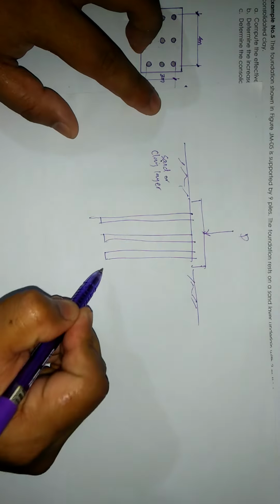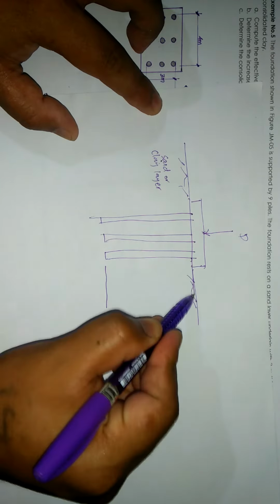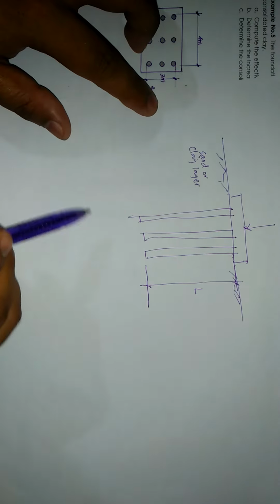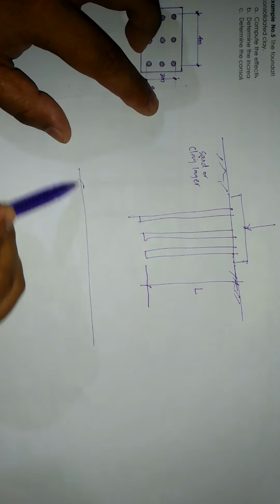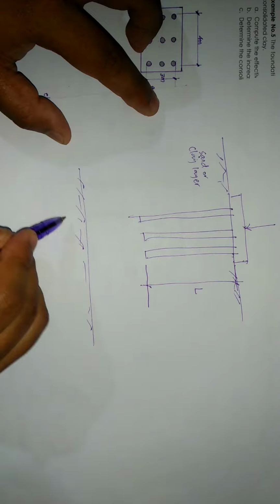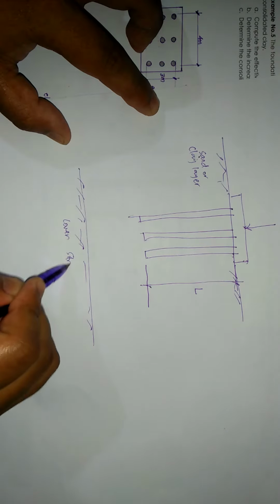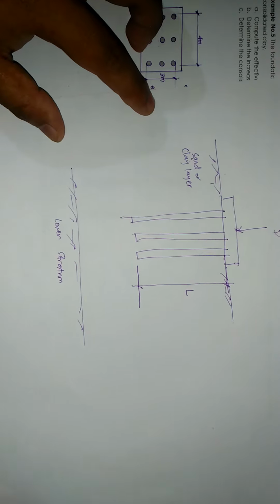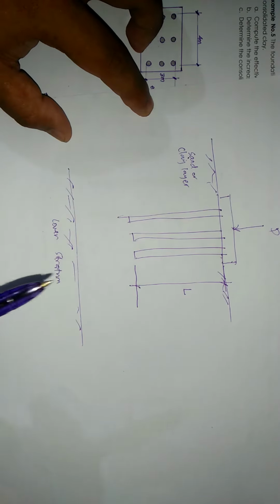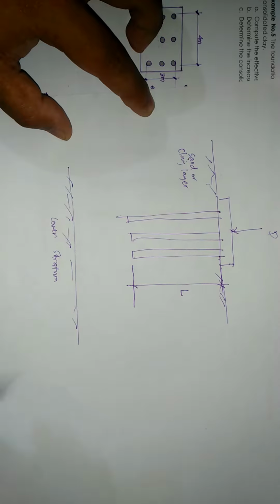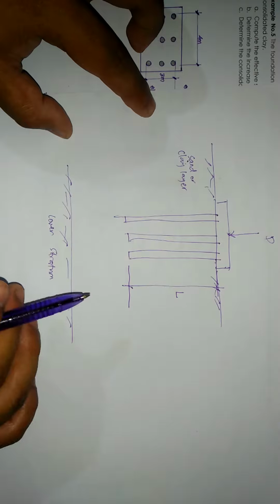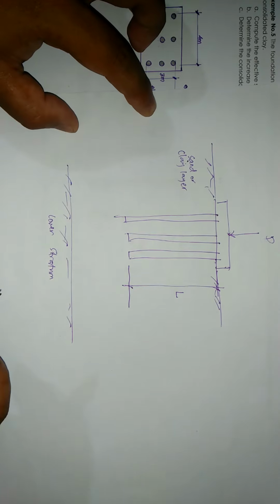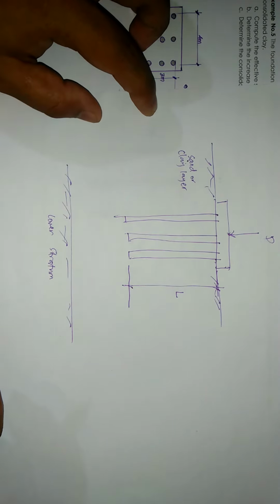Like for example, kung ito ngayon yung length of pile mo, L. And let's assume that this one would be your lower stratum. Yung settlement of a pile group can be estimated by assuming that the supporting block extends to a depth of only 2/3 of the pile length.